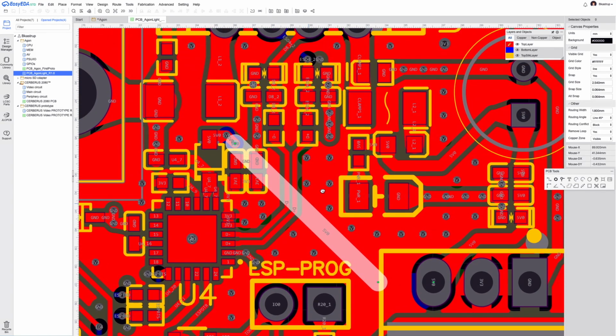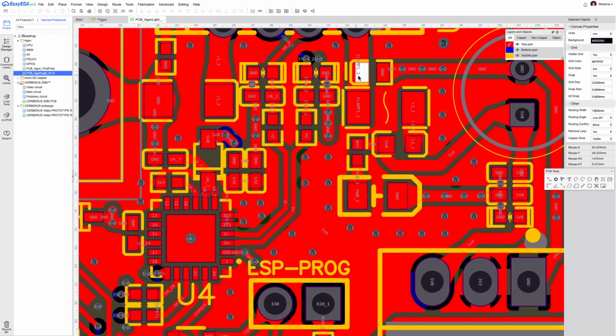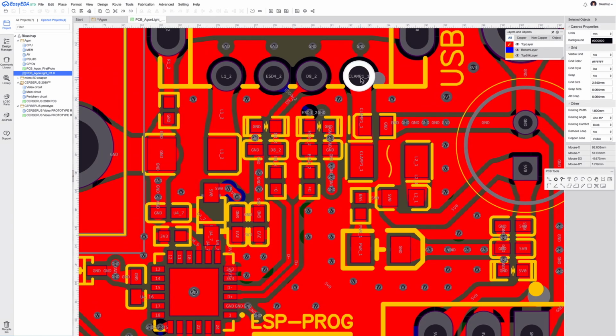Now, on this side here, that's just the protection circuitry. So this is the power line. This is the 5-volt line that comes from USB. So there is a little clamp for excess voltage. There is a fuse for excess current. And then the rest you've seen.